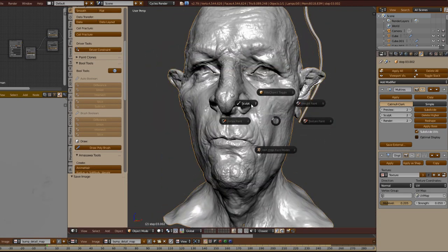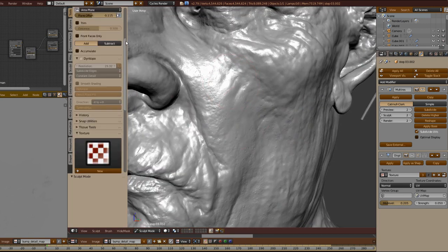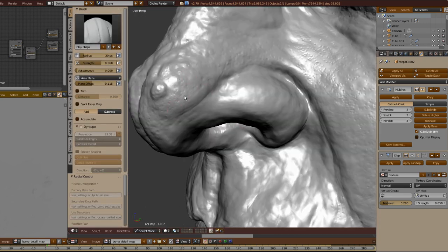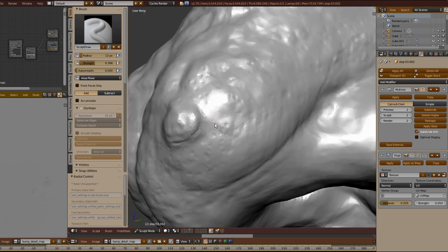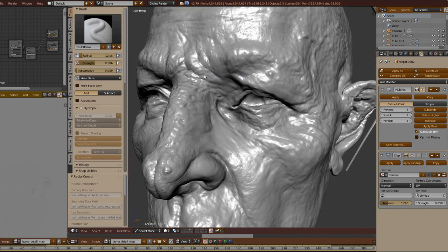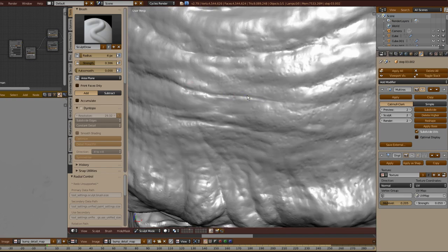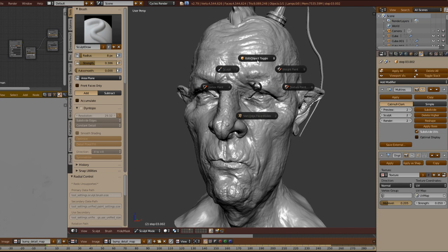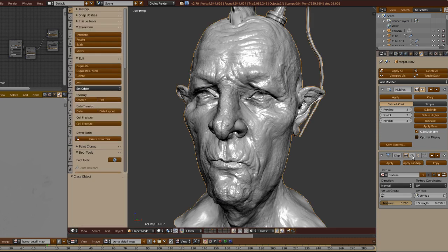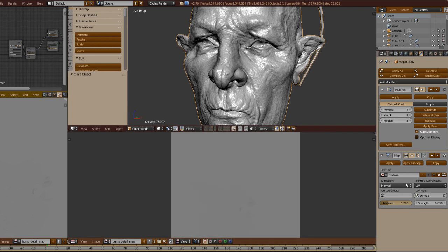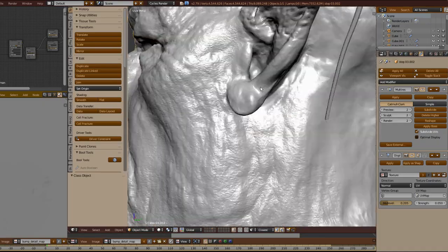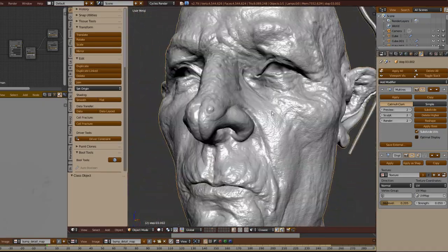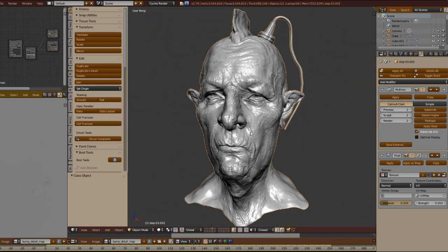With the detailing map done, I went back to the sculpture, increased the subdivision, and I began to unify and further detail the sculpture. In the second level of subdivision, I was able to sculpt extremely sharp and quality details. I confess that I felt a great difference in the quality of my work. After I finished, I added the displacement modifier and I loaded the detailing map that was previously painted. As you can see, I have a non-destructive process, and at any time I can paint and adjust the detail map separately from the sculpture.